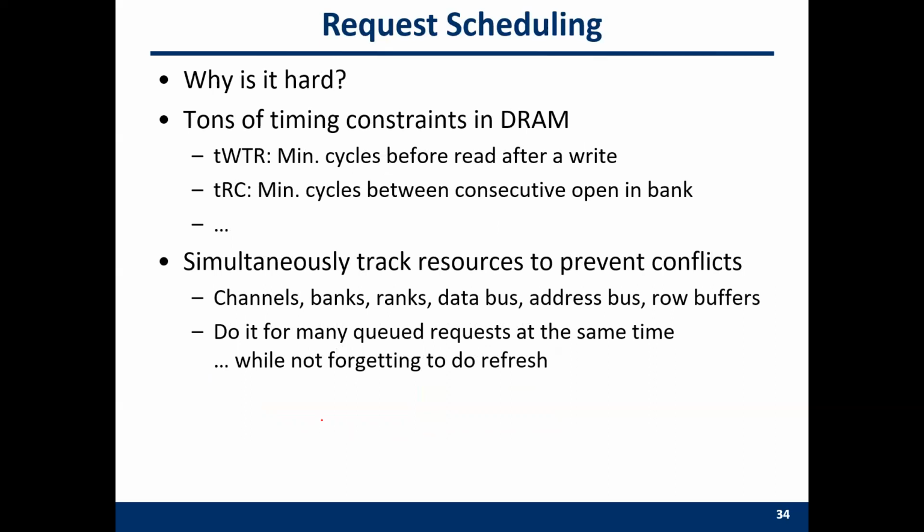Actually, scheduling those requests is very difficult. Why? Because you have a lot of timing constraints. Now you have DDR, DDR2, DDR3, DDR4. Very soon you will have DDR5. These DDR standards will have different timing constraints.